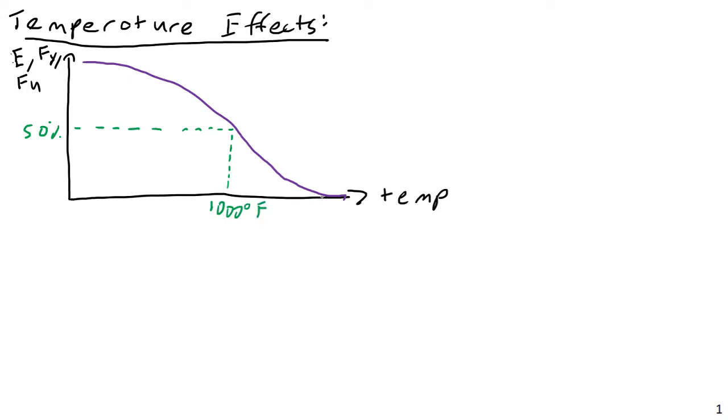And this is ultimately what allows us to hot roll steel shapes. We don't actually have to heat these things up to the point of being molten to form them. We can heat them up to, say, 1,000 degrees Fahrenheit. They're still solid, but they're very pliable solid. If you heat them up enough, they become like clay, although you don't really heat them up to that point. But if you take away 50% of their stiffness and strength, then they become much easier to form. And their actual melting point, or the point of zero strength, might be around 2,000 Fahrenheit or so.